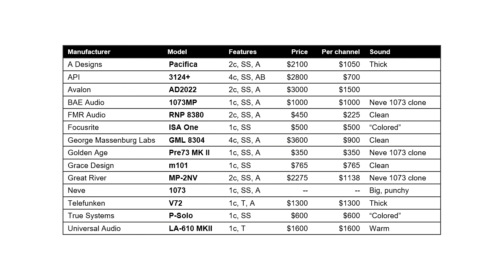Another classification considers the design of the internals of the preamp. There are 3 main designs: Class A, Class B, and Class AB. Class A designs signal the fact that both the positive and negative voltages are simultaneously amplified. This means that the output signal's shape is very close to the original, no distortion. But it also means that the device will run very hot since it is functioning all the time. This means more risk of failure.